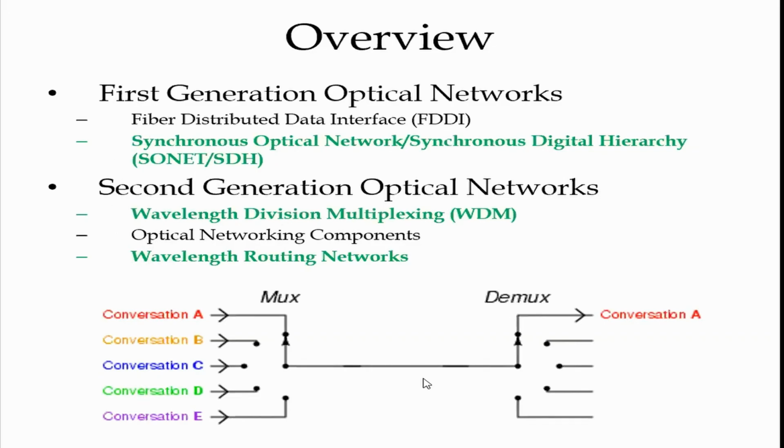This is an example for multiplexing, how multiplexing is happening. You have multiple data. In order to organize it in a synchronous manner, you need mux and demux at transmitter side and receiver side respectively, with a proper clock. If the clock is proper, synchronization will be happening. If the synchronization is better, multiplexing and demultiplexing will happen in a proper manner. So multiple user data are transmitted over a single fiber. This is a fiber connection, and this is your synchronous optical networking backbone. So let's see what is SONET here.